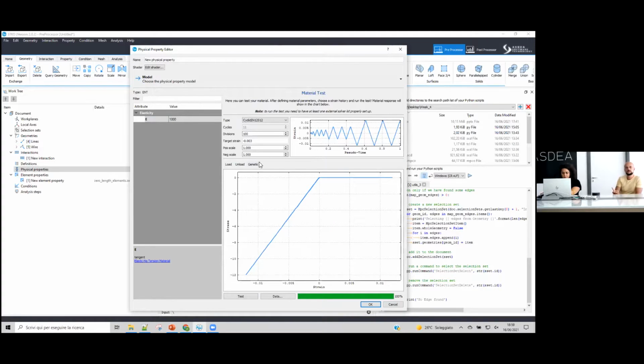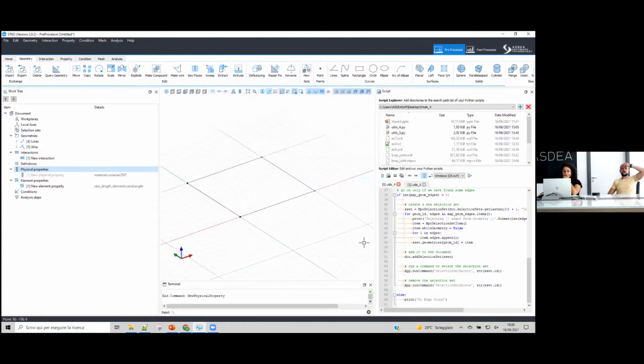and this is useful to simulate in a simple way unilateral contact, but without friction, because this is a simple spring, so it will just prevent normal penetration. If you want a more sophisticated approach to contact, you have zero-length contact elements that have a coupling between normal contact and frictional contact, but they are typically used in detailed contact modeling. So in your case, I think it is sufficient to put some zero-length elements between the beam-column joints of the different buildings with an elastic no tension material. That should be sufficient.